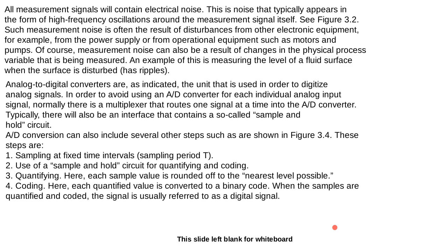And to avoid using the AD converters for each individual analog signal, normally you use a multiplexer that routes one signal at a time into this analog to digital converter. And there will be an interface that contains a sample and hold circuit. This is under the multiplexers.